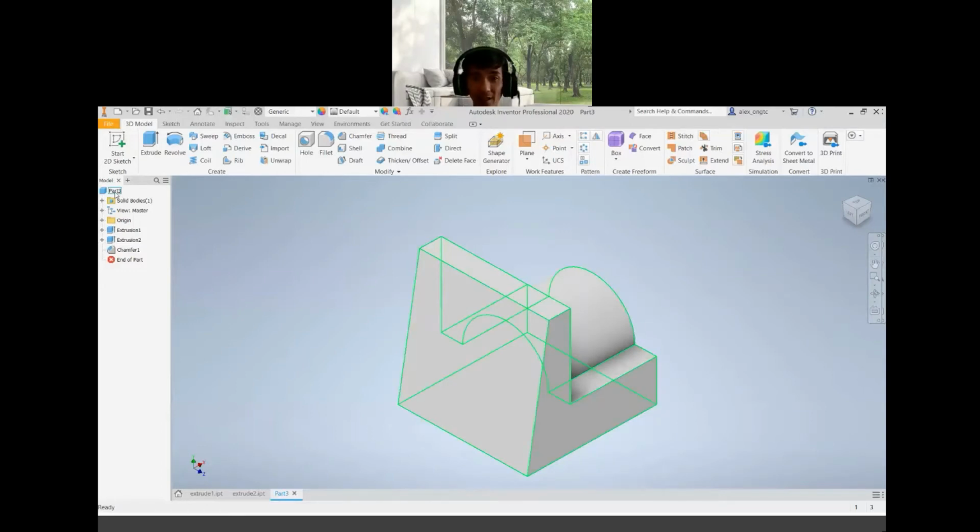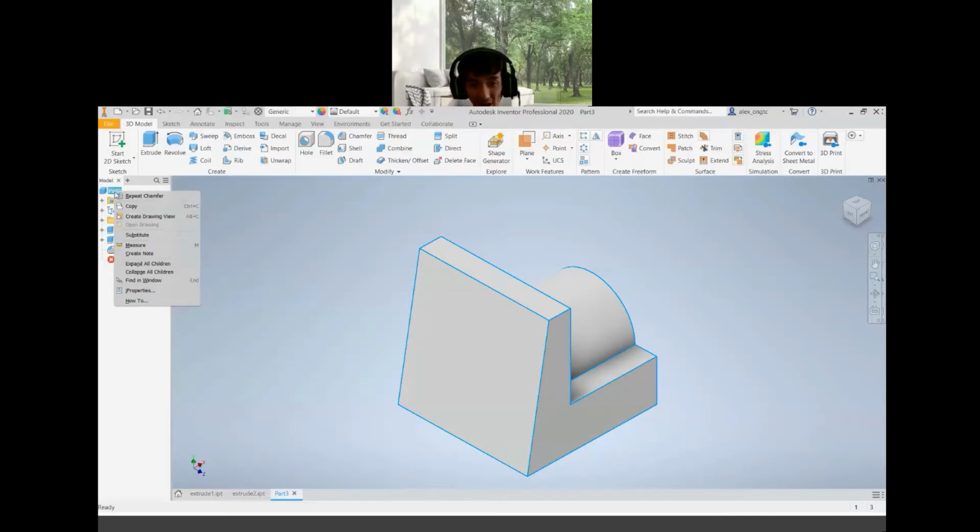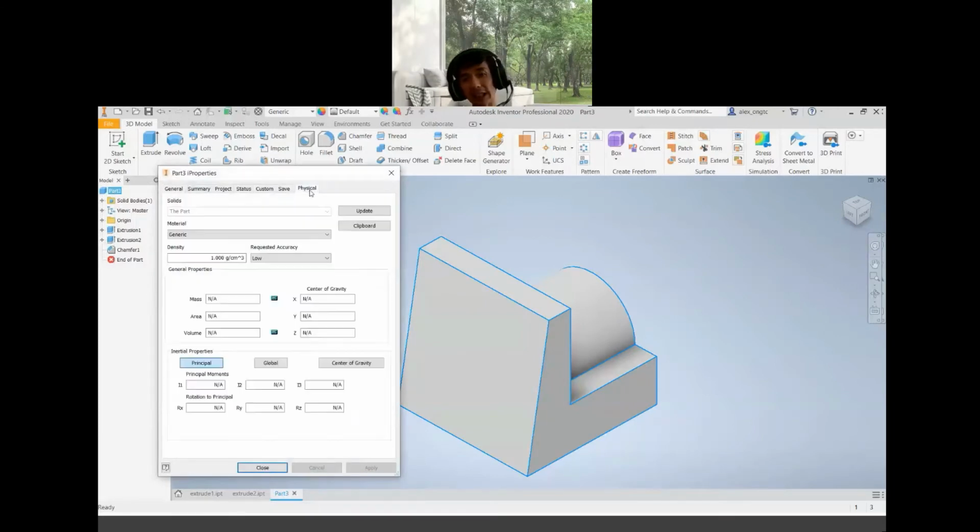So you can, don't click on the placement first. Right-hand click, you can change the dimension type to radius. Now it's radius, you see? If you want this one to be diameter again, don't click on the placement. Right-hand click, change the dimension type to diameter. That's how you change the type of the dimension. So I will leave this one as radius 1. It should look like this in 3D.